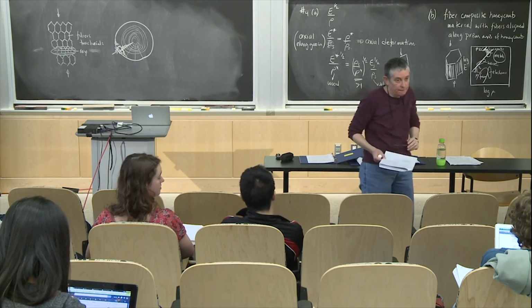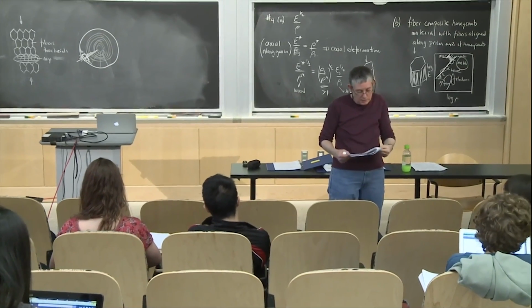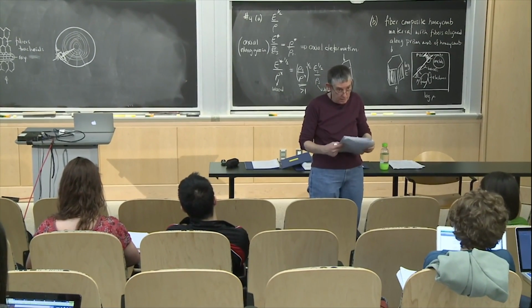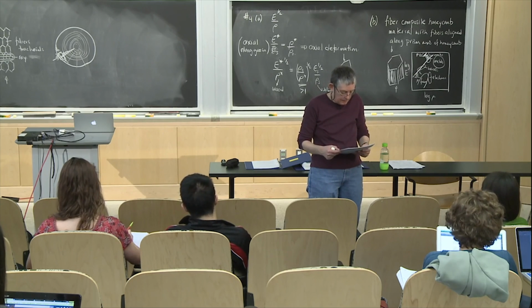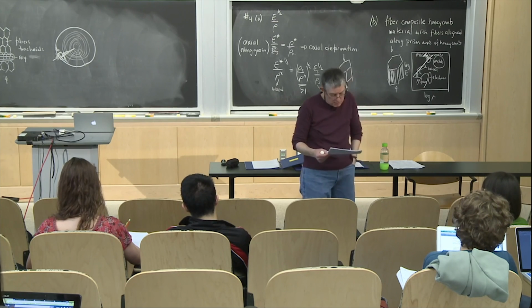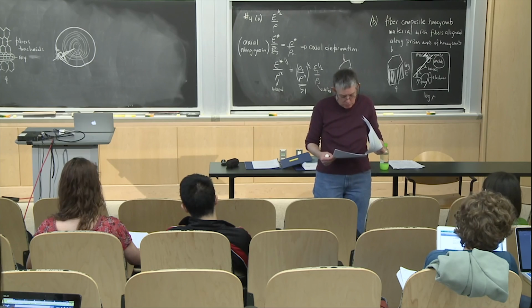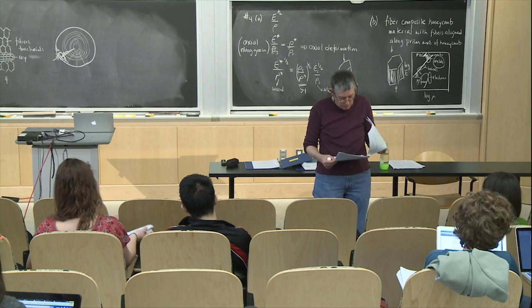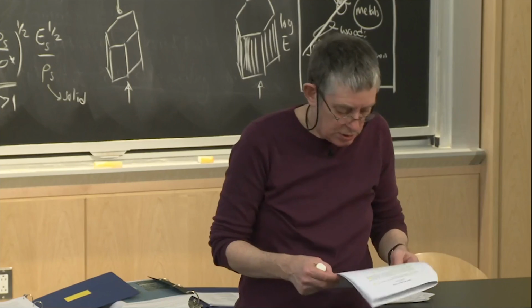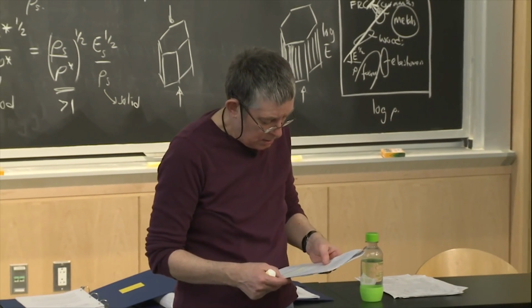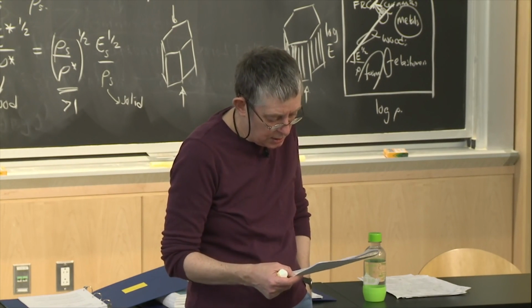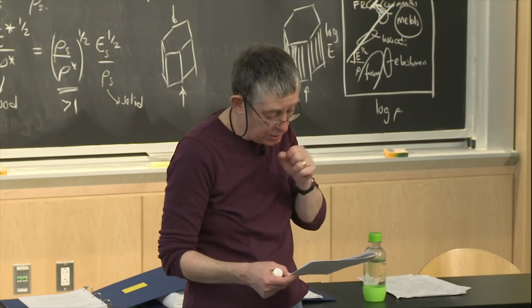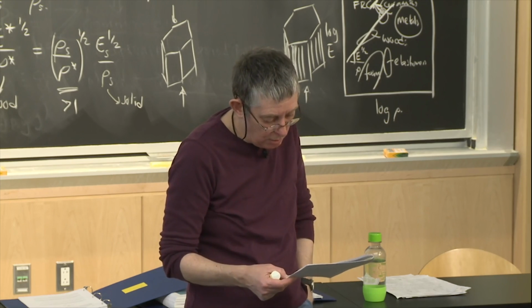For 2, part D, I don't think we went over that, but I was confused as to how, I guess, is it just that equilateral triangular cells is always truss behavior? Let's see. Which is the 2014 test? 2014. Oh, sorry. I missed a part. Yeah, so it says the same titanium alloy is used to make a honeycomb with equilateral triangular cells. And what is the in-plane Young's modulus for loading in the x2 direction of the triangular honeycomb?